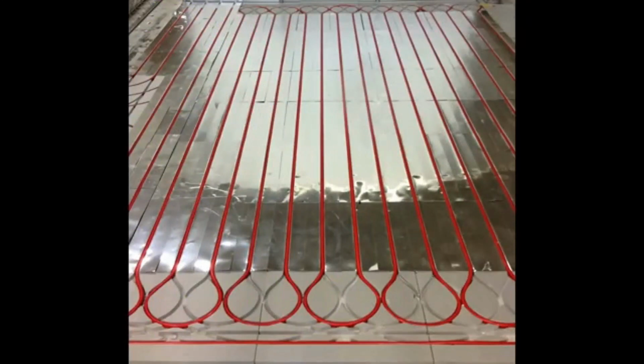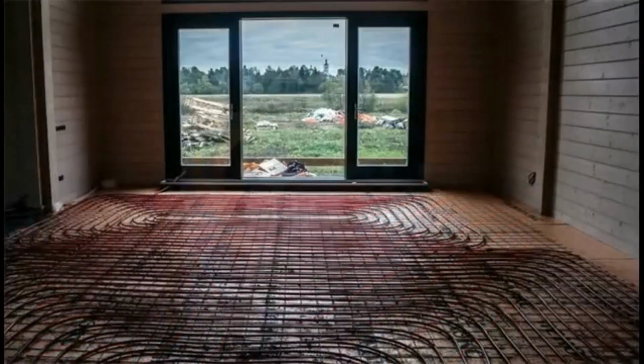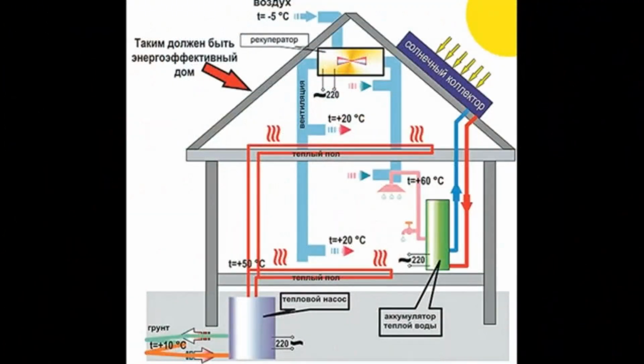If the task is to make a warm floor at the stage of capital construction, definitely make a concrete underfloor heating of traditional construction; on the ground floor it is more rational. Because in any way you need to fill the screed, and it costs nothing. At construction stages, put enough insulation layers, lay pipes and fill them all with the final screed. The only drawback of such a system is that it is sufficiently inertial and it's very difficult to regulate it exactly. As one of the criteria for energy efficiency and energy saving is that we should use energy when we need it and not use it when we don't need it.